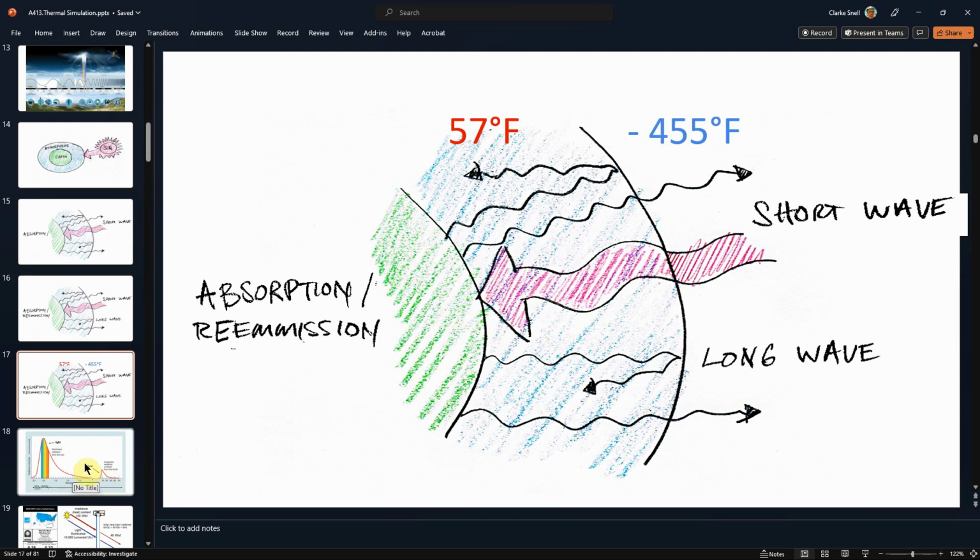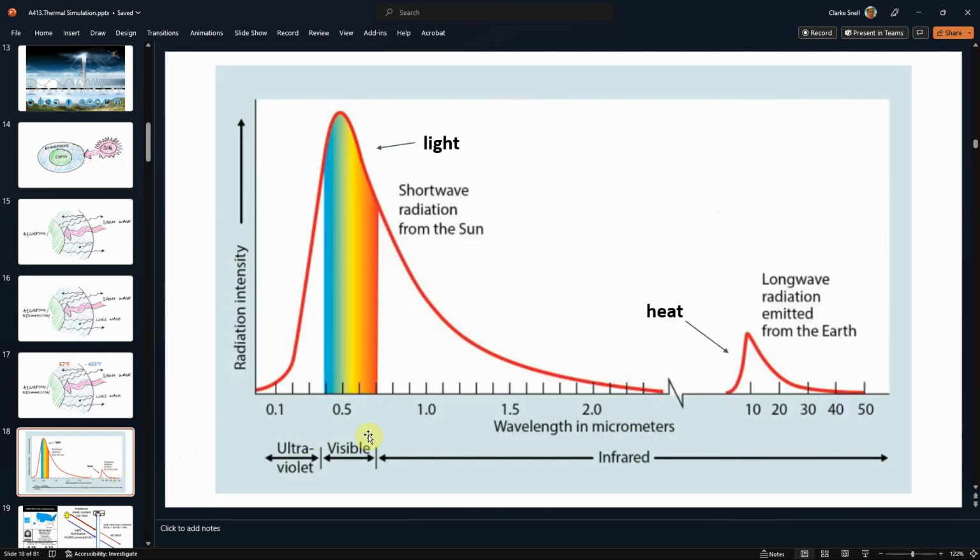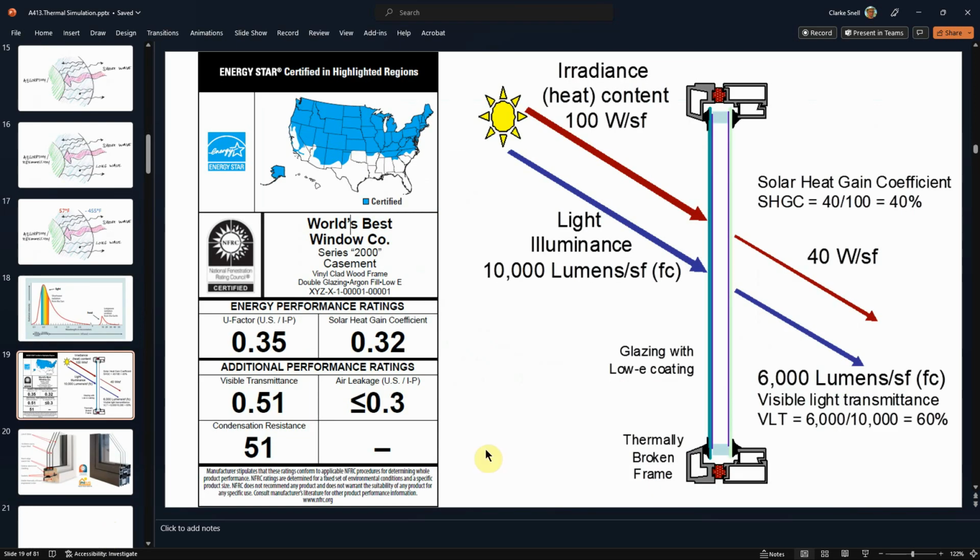And we can take advantage of this same reality in the design of glazing, because what we're saying here is that the wavelengths for visible light are very different than the wavelengths or frequencies for heat. And so we can design glazing units, often, to code always more than one pane of glass at a time in a package, that allow different percentages of light and heat through them.